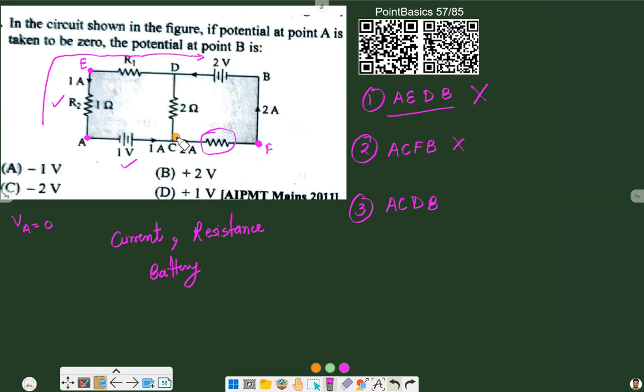So we have to find the current from C to D or D to C. Let's consider point C. For point C, incoming current and outgoing current should be equal. Incoming current at point C is 1 ampere and outgoing current is 2 ampere. So here we have a difference of 1 ampere, and that 1 ampere will be provided by DC. From D, if there is 1 ampere current downward, our equation matches that: 2 ampere coming and 2 ampere going. So that's how we can balance it.